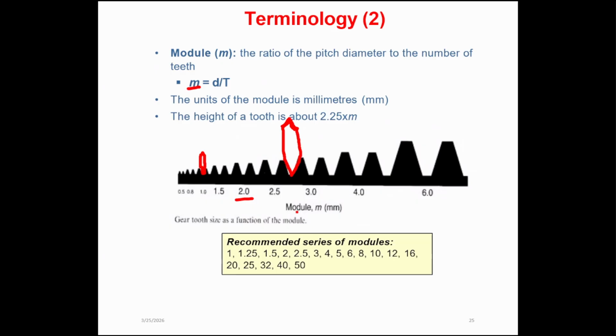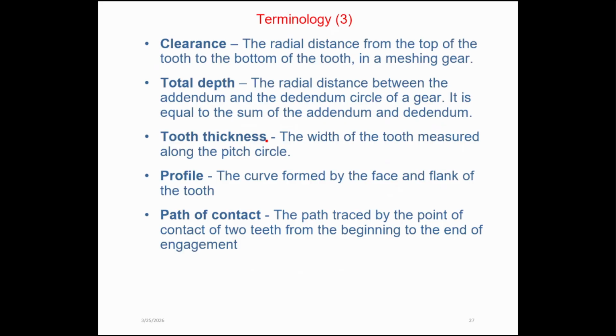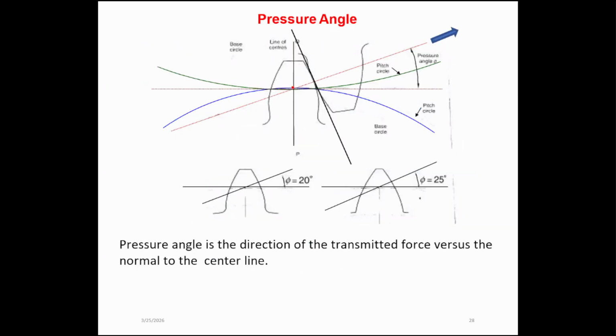Right, it seems right. All the things that we discussed regarding terminology are listed here, right? Yes, one thing, profile. Profile was not discussed. So let's discuss the profile and also the pressure angle. The pressure angle is the direction of the transmitted forces versus the normal to the central.